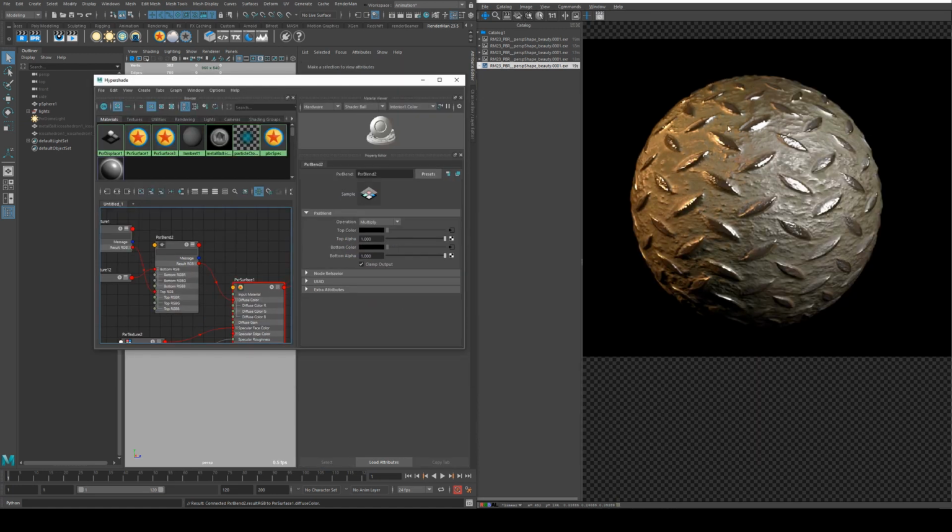So for reference, this is without the ambient occlusion. If we render the ambient occlusion, this is with the ambient occlusion. So if you switch between the two, not a huge difference. You'll see a value shift. That's because ambient occlusion has a lot of dark areas, which simulate occluded shadow in tight spaces. So if you're trying to maybe get a little bit more detail out of your texture map where you might have some cracks and things like that, and you want to show that up a bit more, you may want to use your ambient occlusion. You could also blend it out using the alpha.